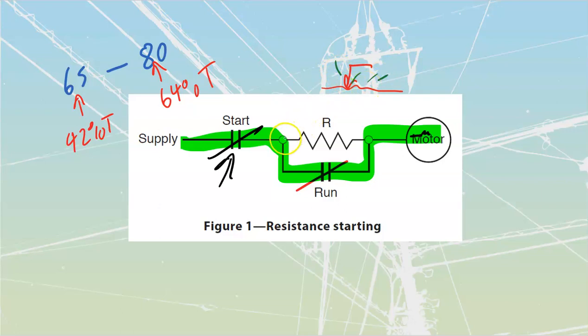What we will do is have fixed resistors, large resistors that are going to be made out of wire or ribbon type or graphite types, or sometimes compressed types. We're going to have large fixed resistors that are bolted into the circuit, and we're just going to bypass them with contactors around them.